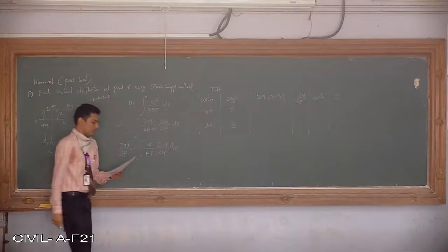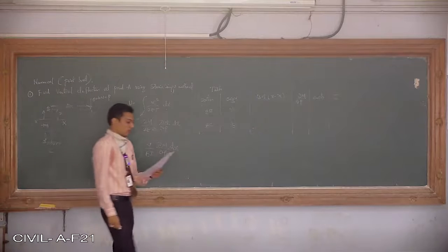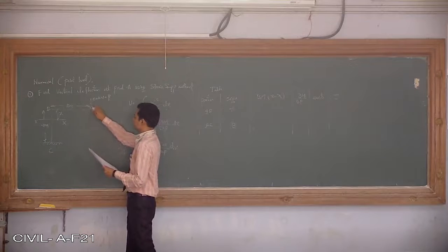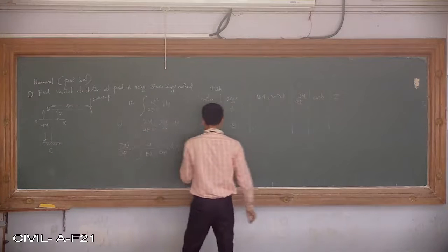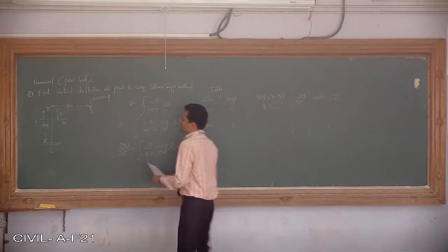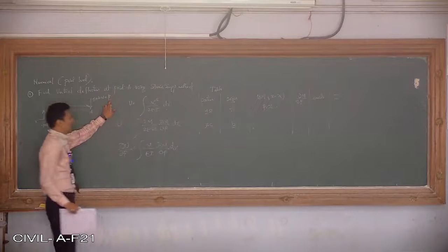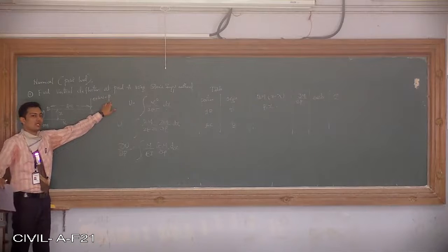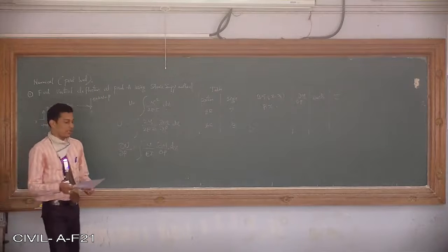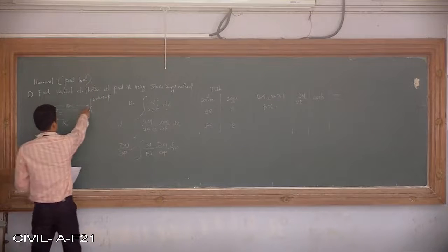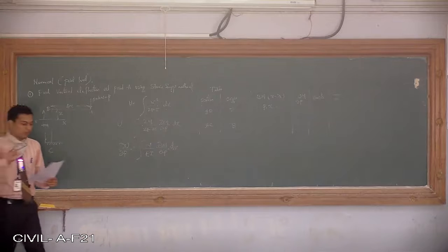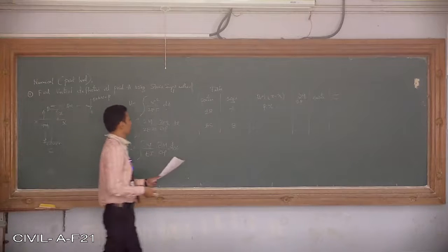Okay. Next, bending moment at section A. You have to take moment about A. What is that moment? It is P into X. Don't take 50 kilonewton because we need to have differentiation with respect to P. Later at last you can put P is equal to 50 kilonewton. Now it is not required to take 50 because if you take 50 into X, you cannot have differentiation part with respect to P. So let it be the variable P into X.